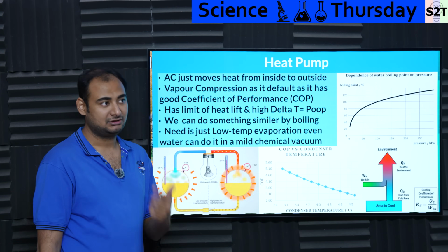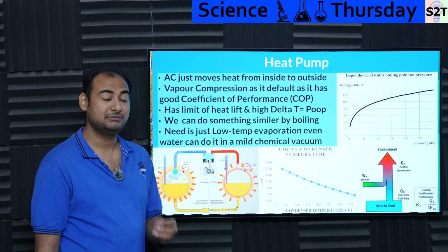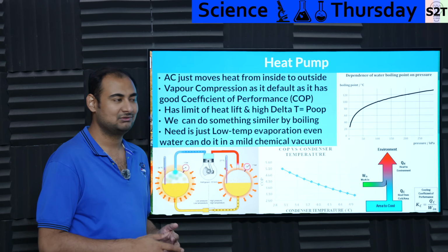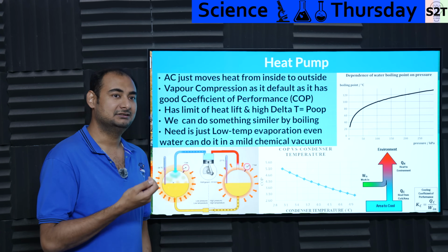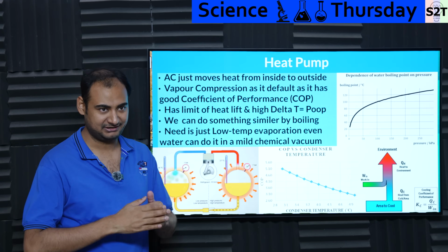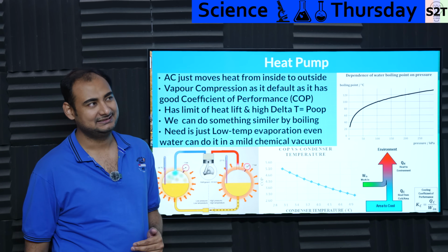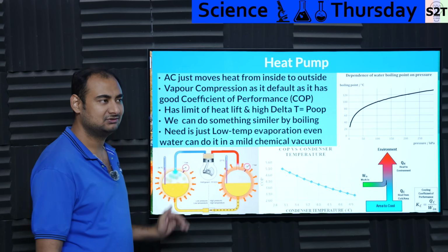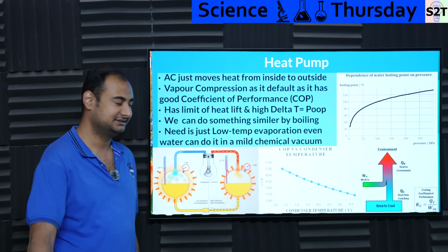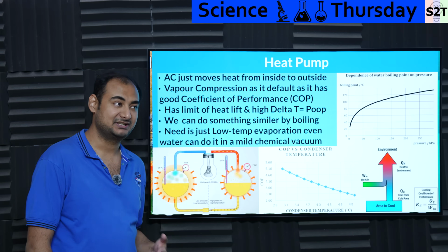And again, be mindful, if you are expecting to run your AC for a very long duration, many times you will find that household ACs use a refrigerant that goes to a very low temperature, because it makes cooling very rapid. Industrial systems have to run 24/7, so that backfires on you. At that point, you do not want the low to go that low. So it's like minus 10 degrees, we're good, we got this. That sort of refrigerant makes far more sense.